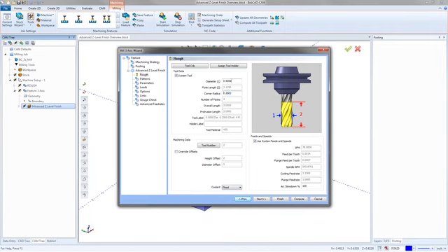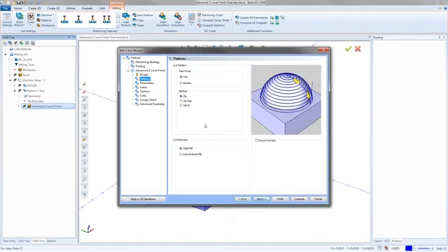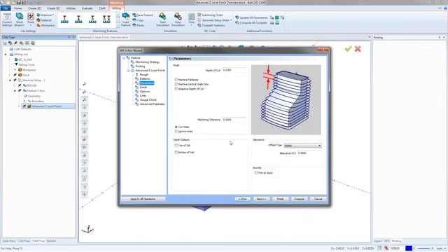So right here we have the tool information, just what size tool we're using, and in this case, it's a ball mill. So 1/2-inch ball. The rough was already done with a flat mill. So right here, the patterns, there's really nothing new on most of these pages. You're going from the top down, the bottom up, however you want to cut. On the parameters page, you have the depth of cut set here. So I got mine set to 20 thousandths.